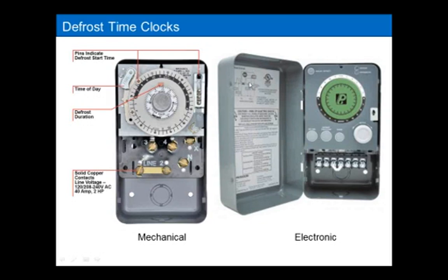Always default to the diagram on the timer itself. That is the best, safest, most sure way of knowing what the terminals identify. But these are where you're going to connect your circuitry to control your compressor, your fans, and your heating.